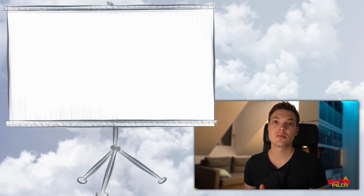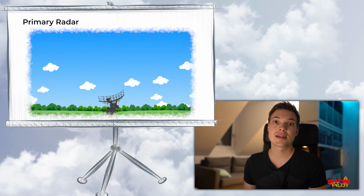Now let's get right into it by looking at some basics. Traditionally, the position of an airplane has always been determined through radar systems. The most basic radar system is primary radar, and that's also called primary surveillance radar. Primary radar means that a radar transmitter emits radio waves which will be reflected by any solid object. The lateral position of an aircraft can be determined like this without having any onboard equipment in the plane.